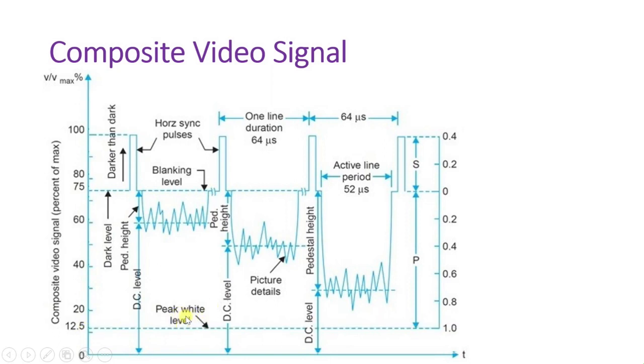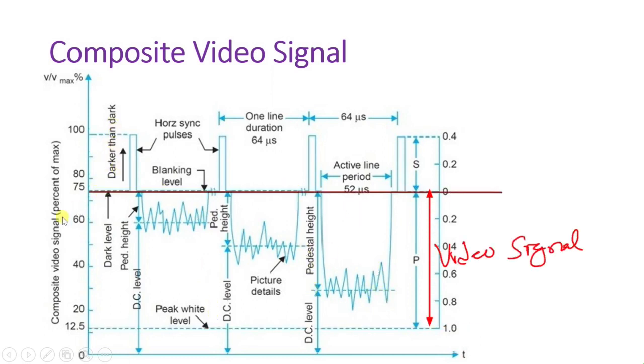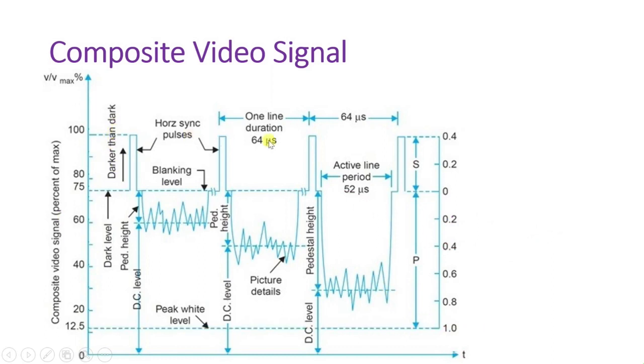Black setup. Note that the black peaks of the camera signal variation are deviations from the black blanking level of 7.5 IRE units, which is approximately 5% of the total. The goal is to ensure that additional carrier signals, subcarrier signals, for colors near black in the camera signal do not interfere with the sync amplitude.